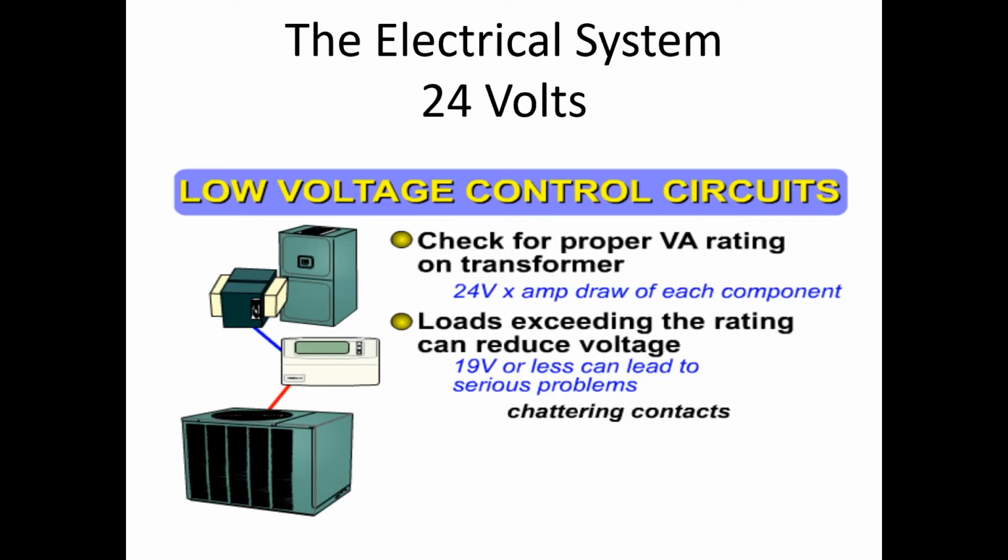As we have lower voltage, our current is going to increase. That increased current causes more heat, and the compressor windings aren't rated for that higher amp draw or that higher amount of heat that they might be experiencing. So if you're having an issue where you've got contactor coils failing, check your voltage.